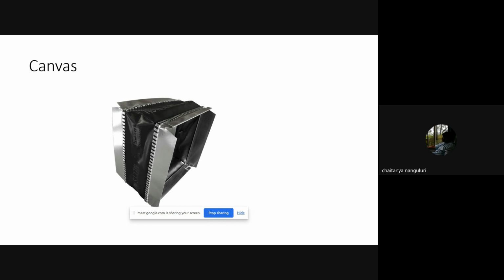to the duct, at that location we will introduce something called a canvas connection, because the unit will have motors that will vibrate for sure. And the blower fan, obviously, when it hits the fan, it will vibrate as well. So that vibration should not be transmitted to our ducting, isn't it? For that reason, we have something called a canvas connection. At the mouth of every equipment, you have to install this canvas connection. Understood? So that even if one end vibrates, that vibration will not be transmitted to your entire ducting.